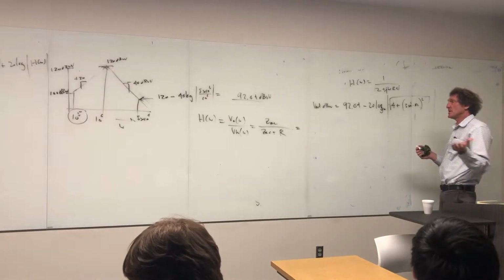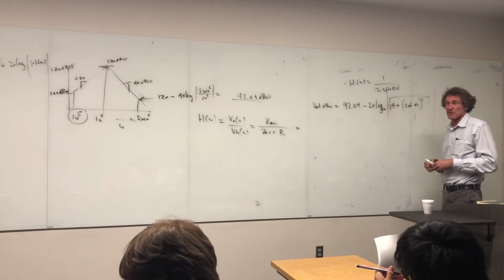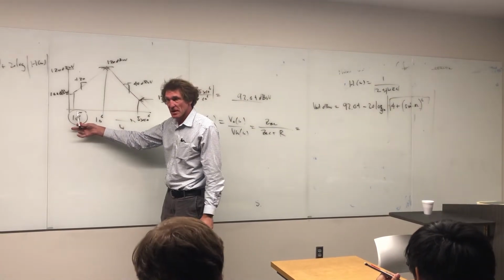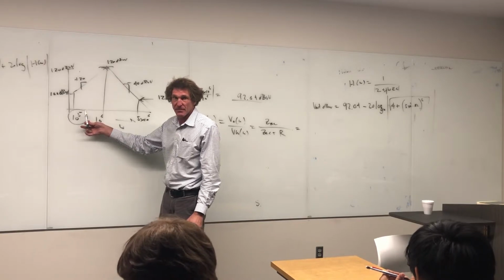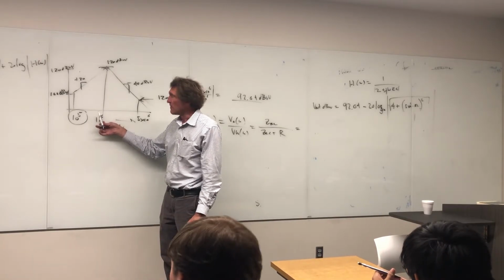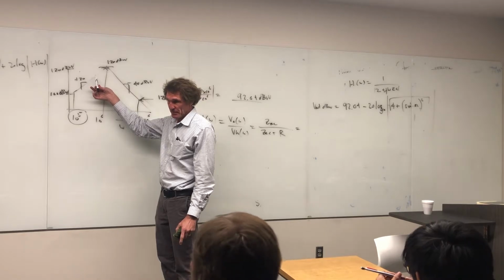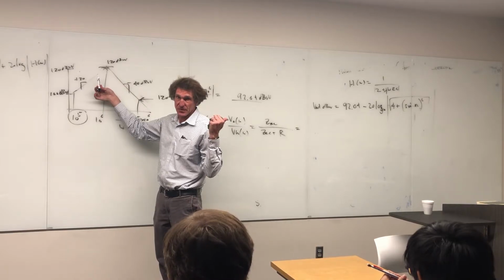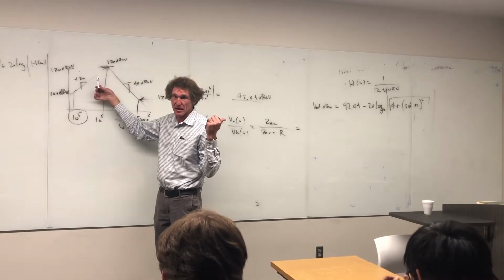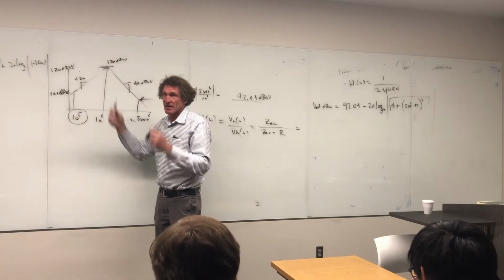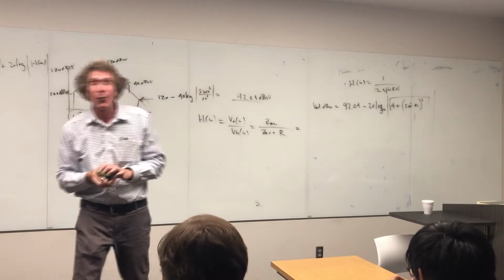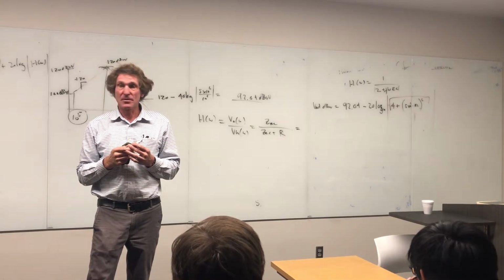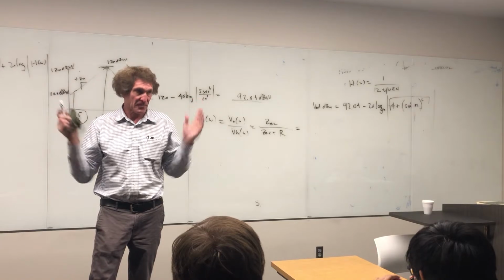There's nothing tricky. If I wanted it for the third harmonic, what would change really? Well, now you go back here, right? There's the first. The second would be 2 times 10 to the 5th. The third would be 3 times 10 to the 5th. Find the input level. After you have that, find the value of the transfer function at the third harmonic, and minus 20 times the log of that, 4 plus 3 omega naught times R times C quantity squared, square root of that.